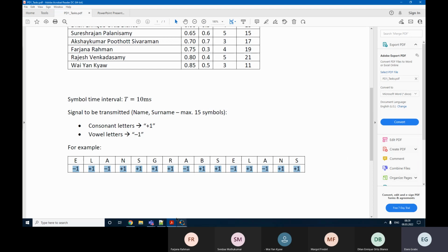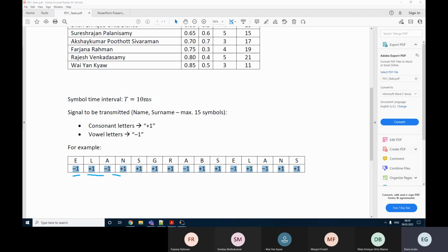And in fact, we now need not particularly this format, but some other format, because for quadrature amplitude modulation, we are going to need two values: one for the x-axis, the real part of the signal, and one for the imaginary part, the y-axis. And the step on each axis is 2 units, like this.